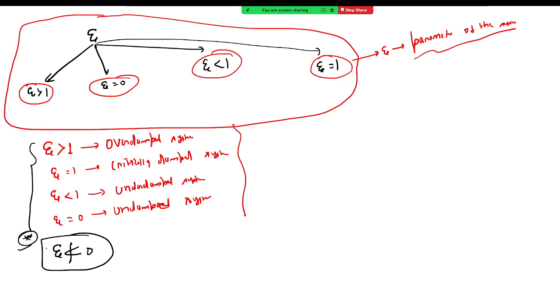It's a very important thing. Based on this zeta, we can plot this second order process and understand it. I have told you that the transfer function of the second order process, that is Y(s) divided by X(s) in terms of deviation variable, is Kp upon tau square s square plus 2 zeta tau s plus 1.